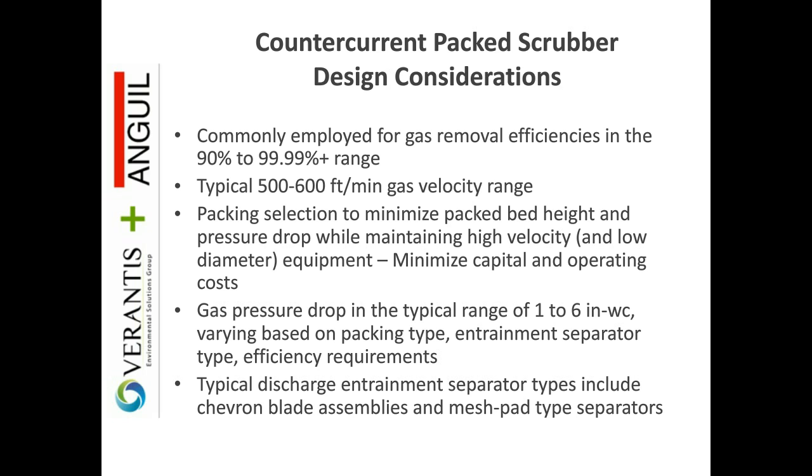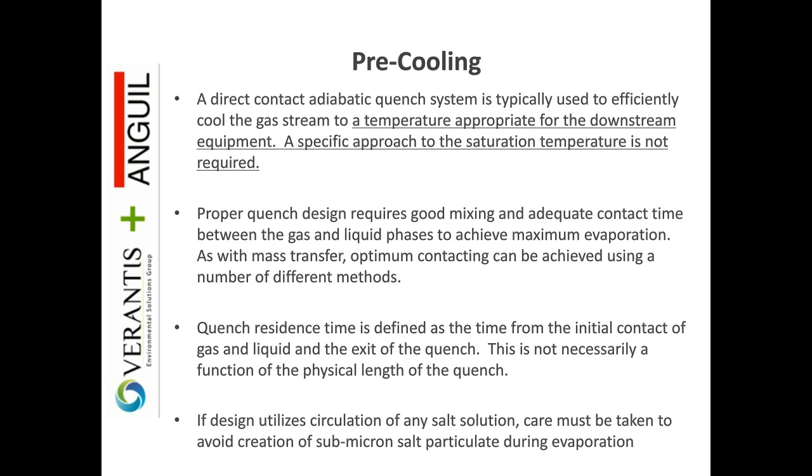One special note for the scrubber downstream of a thermal oxidizer. No matter what the type of thermal oxidizer is, the gas is typically going to come off at a fairly high temperature in comparison to the scrubbing equipment itself and what it can withstand. So we have to integrate a pre-cooling stage. Typically we're looking at a direct contact adiabatic quenching system where we're just contacting a relatively large amount of water with the gas stream itself to drop the temperature rapidly.